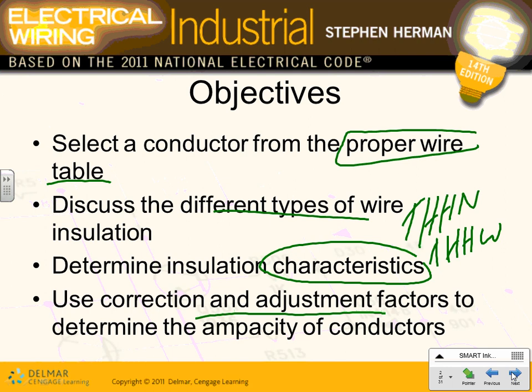The only time it makes sense, Jeff, to group things is if they're branch circuits, and if you're feeding them with number 12 or number 10. That's when it makes a lot of sense to group them. So if I have a 3-phase motor, and that 3-phase motor did the calculation, you need 3 conductors, number 10.